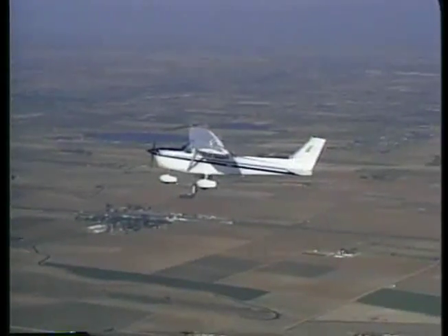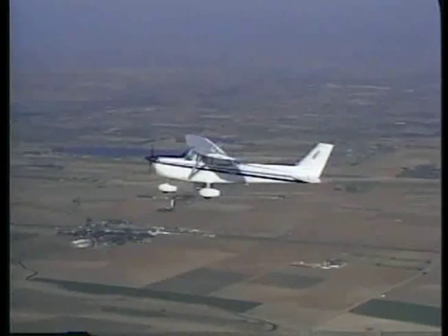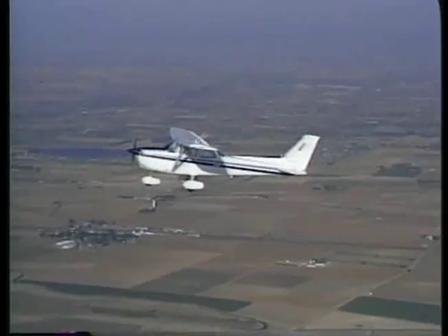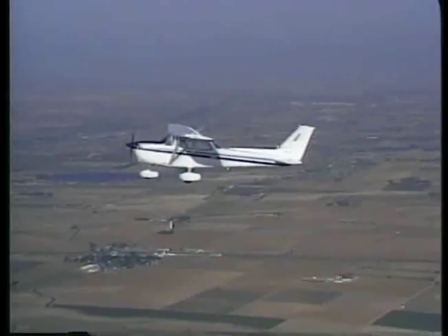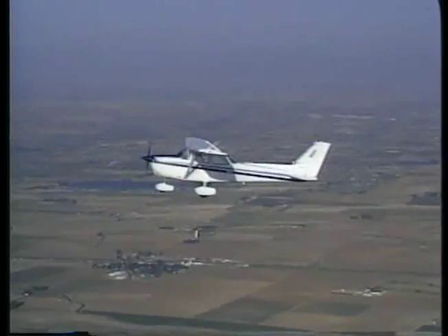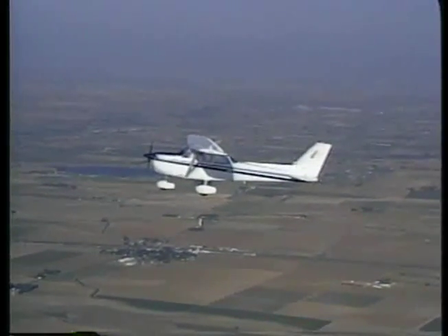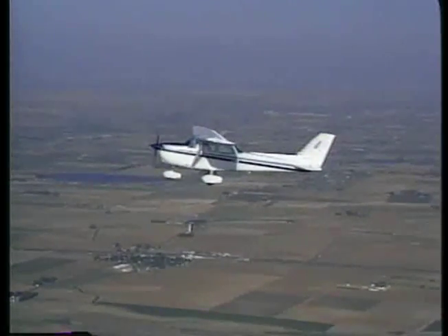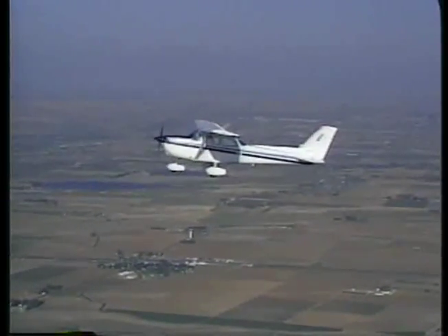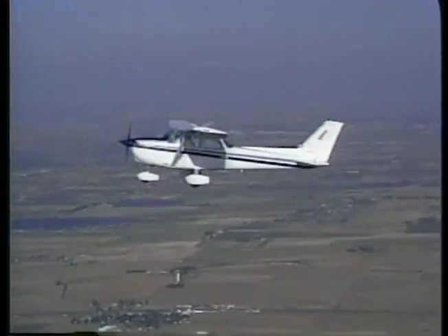As you continue your training, you will be introduced to more advanced flight training, including maneuvering during slow flight. Slow flight can be thought of as any airspeed below normal cruise. However, during your training, slow flight will typically be conducted at an airspeed where any significant reduction in speed or power or an increase in load factor results in a stall indication.